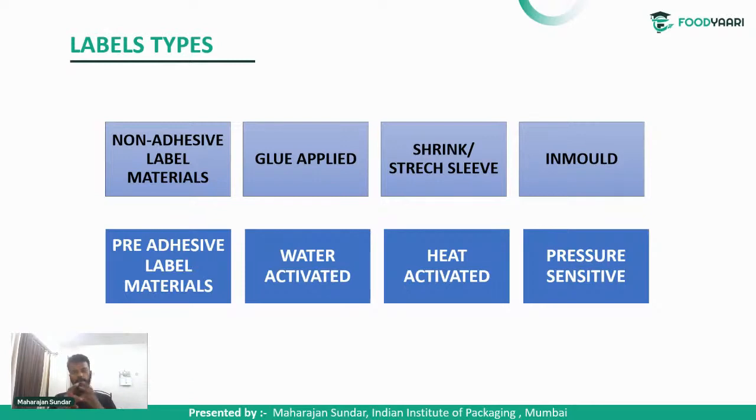In-mold labeling is a brilliant technique, but it is not used majorly due to limitations in cost. While making the bottle itself, the label material is placed inside the mold, and then the bottle is made. It is done only for rigid materials. Before the rigid material dries, the label is fitted, during its natural drying process.